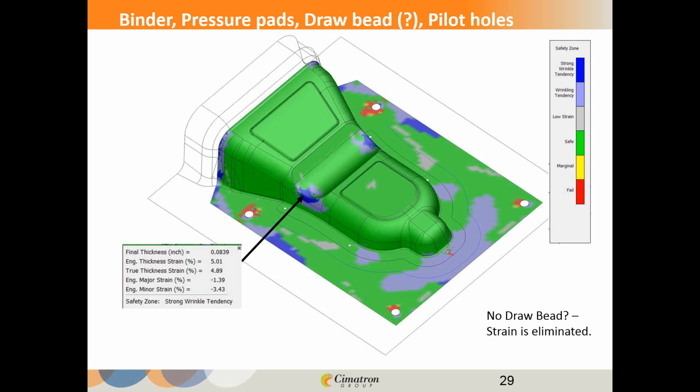So it helps me to stop and think about what I'm doing as I'm doing it. Imagine yourself out there at the press. You set this die up for the 5th time now, and you smack it, and sure enough it tears right where that draw bead is at. So now your frustrated foreman says, that's it, I've had enough of this, I'm sick and tired of taking this die off. He goes and gets a disc grinder and he just grinds that draw bead down because he knows that's going to work. Is that going to be the way you want to solve the problem? Well, clearly it makes more sense if we can control the process and look at what we're doing here on the computer screen. We're going to have a better product to take out there when we start doing our die tryouts.